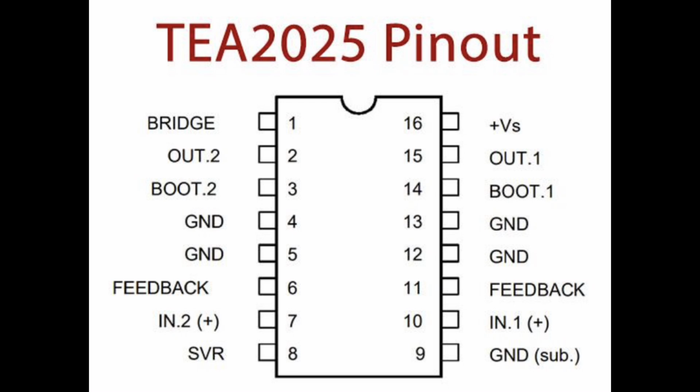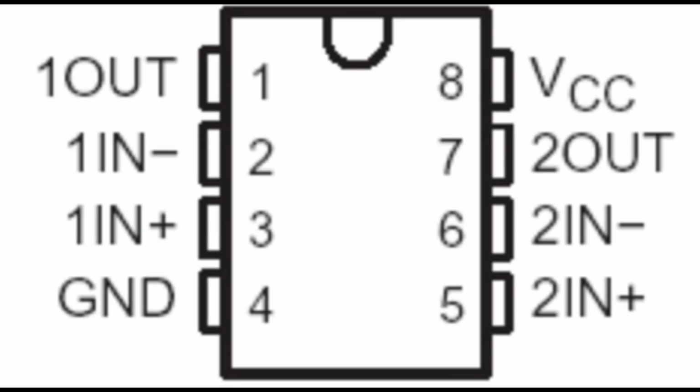The signal amplification is adjustable based on external components, like resistors and capacitors, allowing for customization of the final audio signal. The LM358 is a dual amplifier IC widely used in electronic applications such as amplifiers and filters. It contains two high-gain operational amplifiers designed to amplify weak signals. The IC is internally frequency compensated, ensuring consistent performance across various frequencies, and is versatile enough to operate with either a single or split power supply, making it suitable for many circuit designs. In filtering applications, it modifies a signal's frequency response, boosting or cutting specific frequencies.